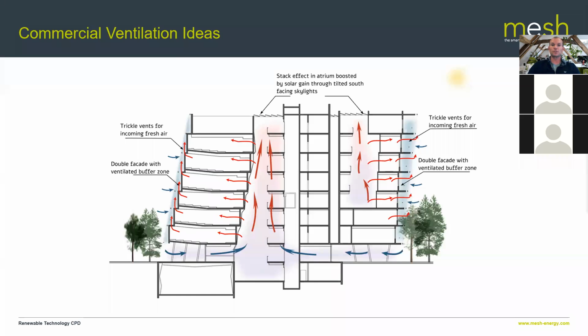But also, this is really interesting as well. As you've got skylights at the top, they can ventilate. But remember what I said about using solar gain to your advantage. As you let more sunlight in at the top of the building here, you increase your thermal differential in the building, and you increase and accelerate the movement of air using that buoyancy and stack effect. So you encourage hot air to get out of the building at high level. And so this particular example uses, again, a few of those different effects where you have those self-contained little areas, but also have central atriums.